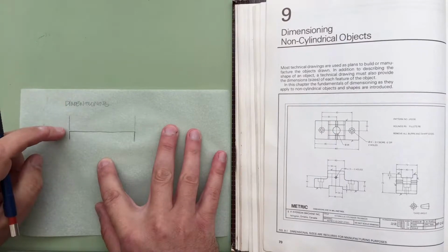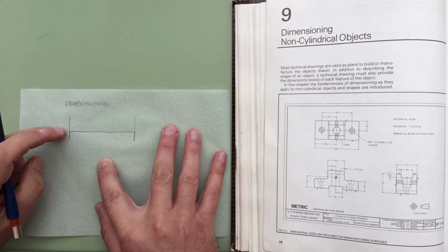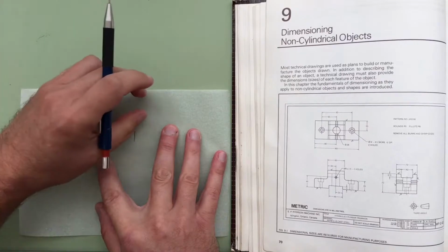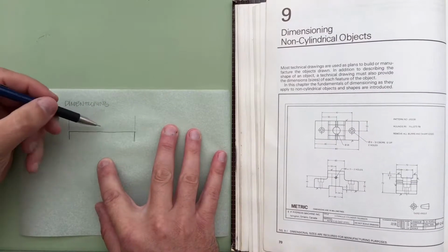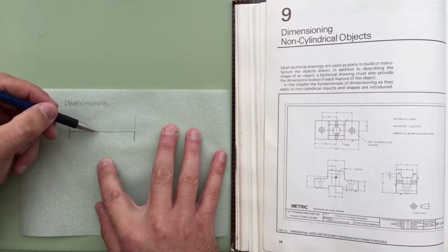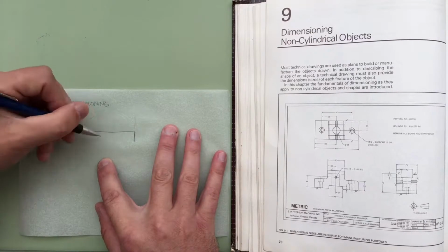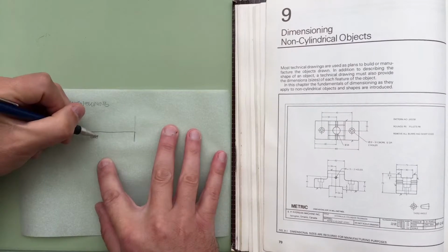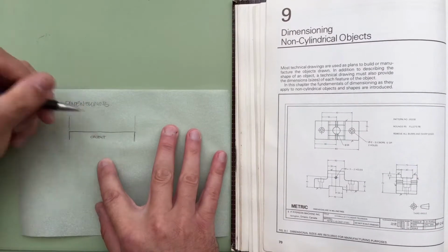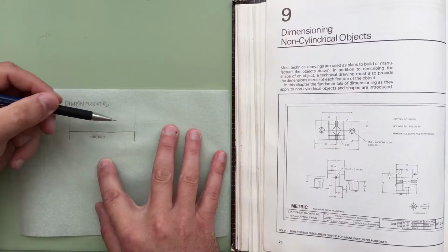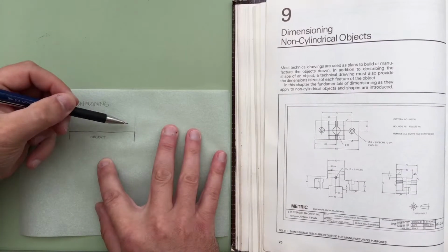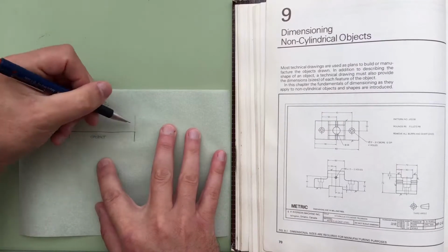Sometimes it can be shorter if there's not much room, or if there's another drawing right above it and we're trying to pack all these dimensions in. But typically we want anywhere from 15 to 20 millimeters of white space between the object that we are dimensioning and the dimension. So we have the witness line that emanates from the corners, and then we have the dimension line.